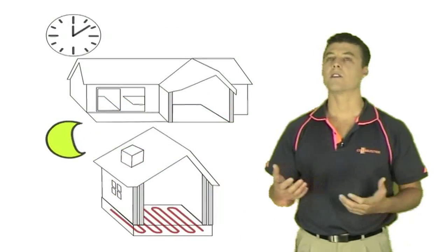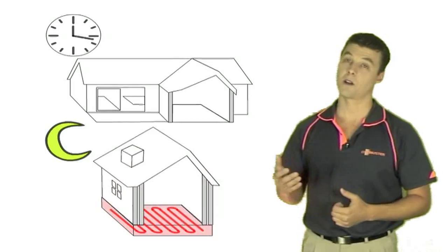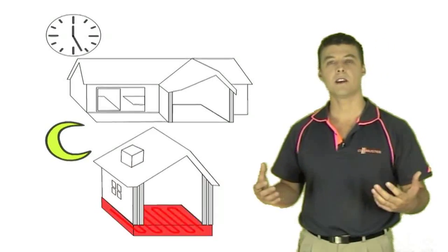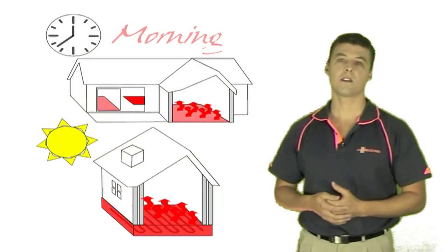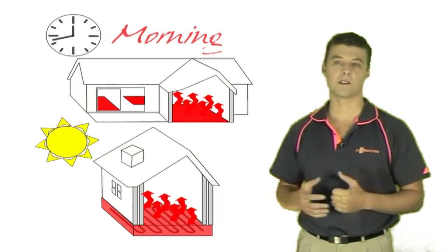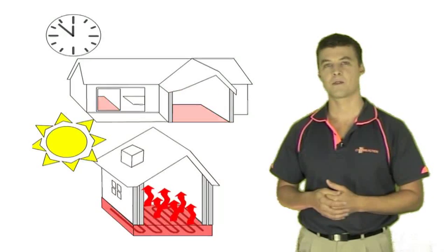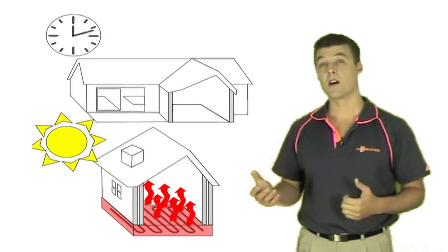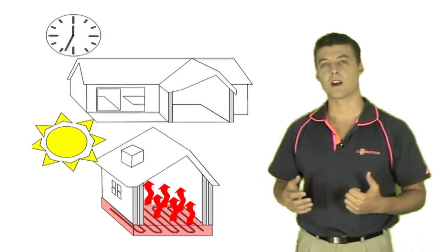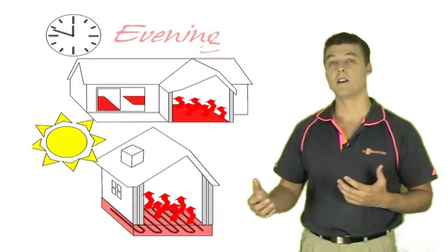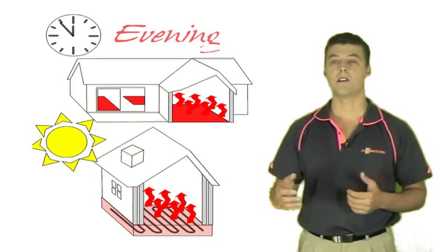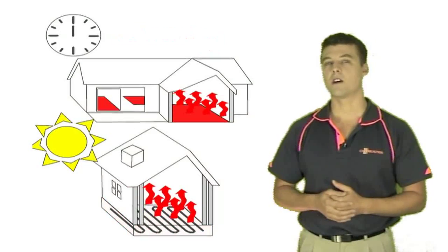Comparing the two, a storage floor heating system works well in Europe because heat is needed for each room on a daily basis over a consistently cold 5 to 6 month winter season. An on-demand floor heating system works better in Australia as the system is quick enough to heat only when required in the rooms that are occupied and does not need to be left on overnight or during the daytime.